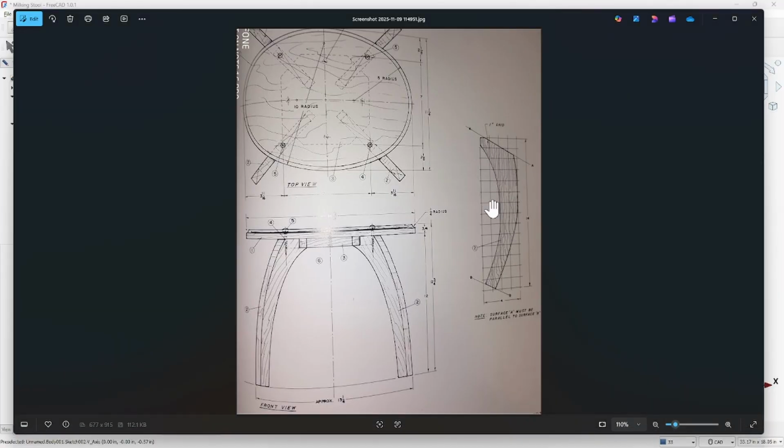We're going to come over. Looks like from left to right, that polyline goes about halfway over and then comes in tangent to that. The polylines, when you want to shape them, you want to start off with as few points as you can. So I'm going to start with 3 points, and then I may add a point. Now if I go 3 points, that's going to give me a perfect arc. So I'm going to go with 4 points. You'll see what I'm talking about.